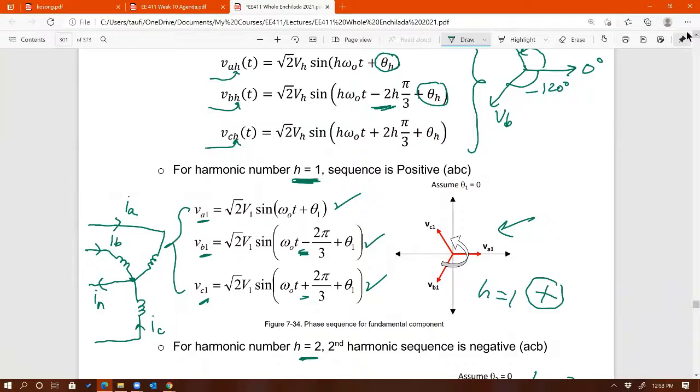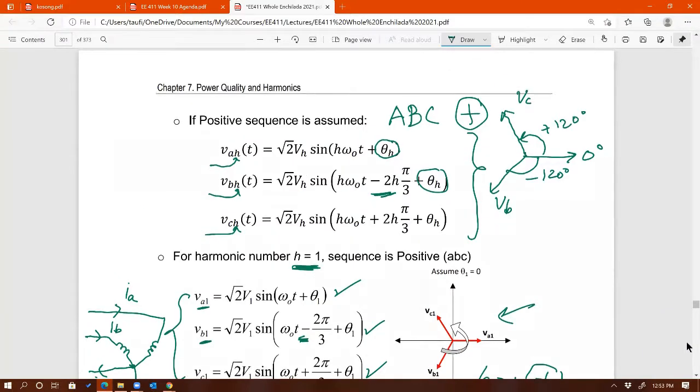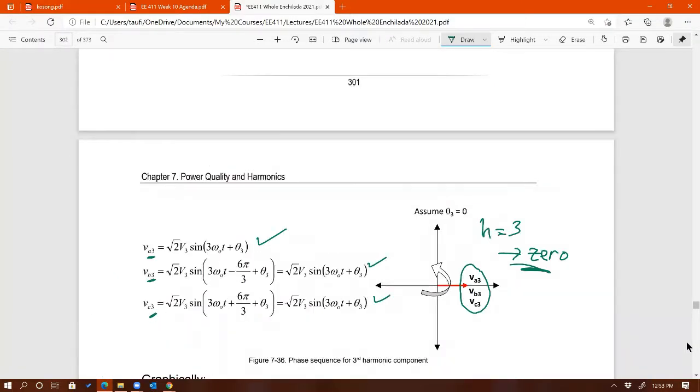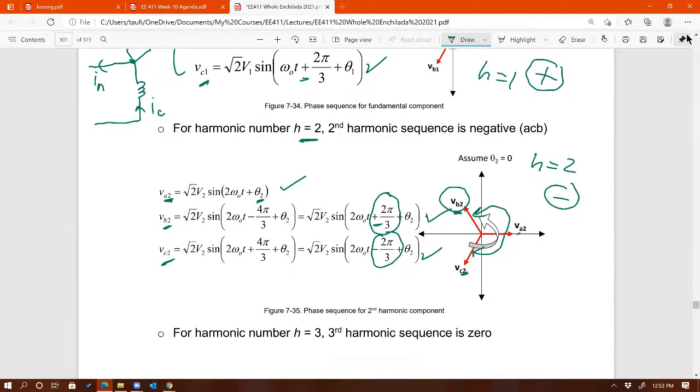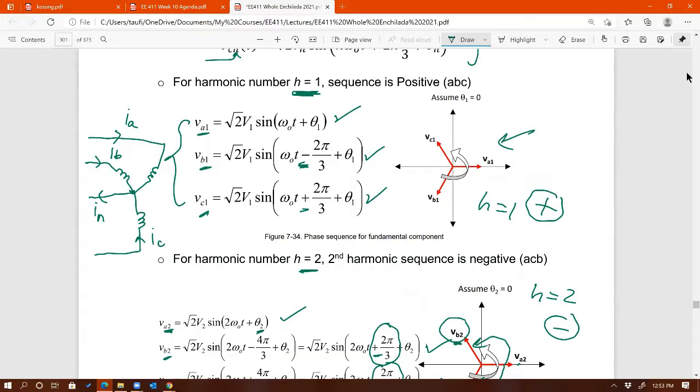go ahead and add. Let me use my mouse. Right there. Let me erase this. Go ahead and change those currents to IA1, IB1, IC1. What happens if you add those three currents? You're going to end up with how much? 0, because they're balanced. If you add them up, it's going to be 0. So IN1 is going to be 0.